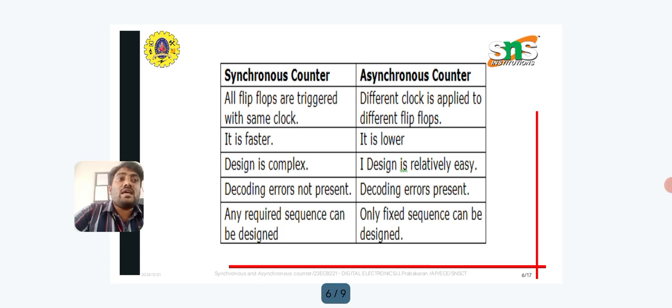Propagation delay is very minimal in the synchronous counter when compared to the asynchronous counter. Considering synchronization, all outputs are synchronized, whereas the asynchronous counter has some lacking.